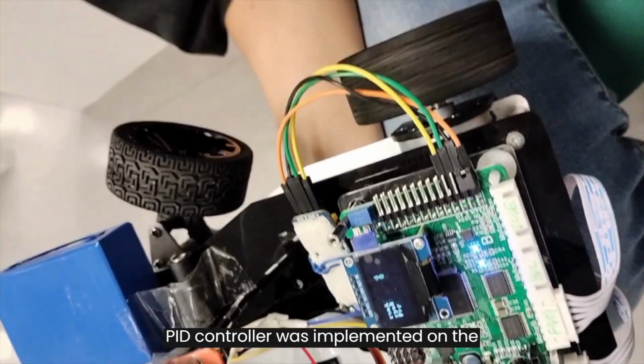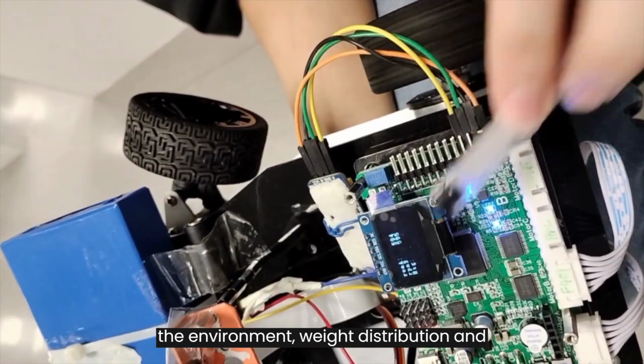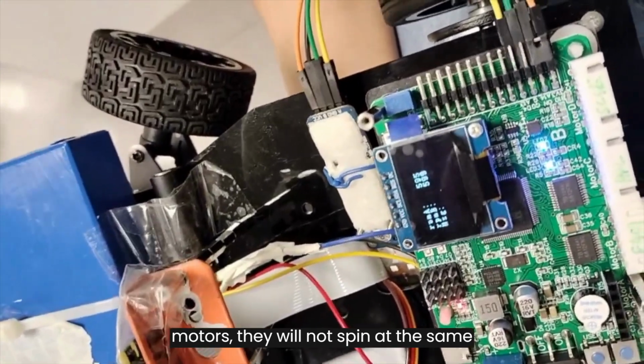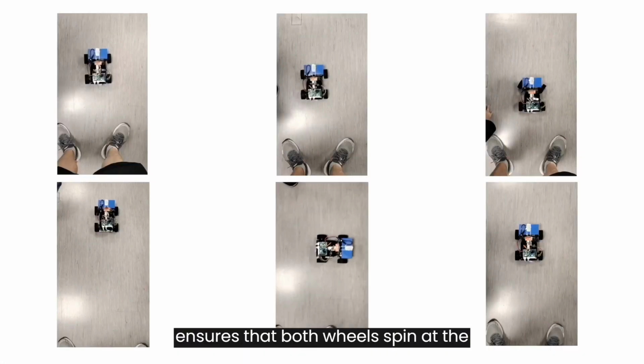The other PID controller was implemented on the DC motor to account for factors such as the environment, weight distribution, and motor setup that can affect wheel turns. Given the same PWM to drive the motors, they will not spin at the same RPM. The use of encoders and the PID ensures that both wheels spin at the same speed.